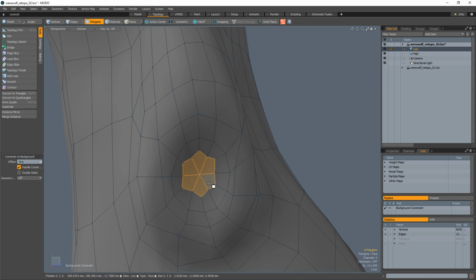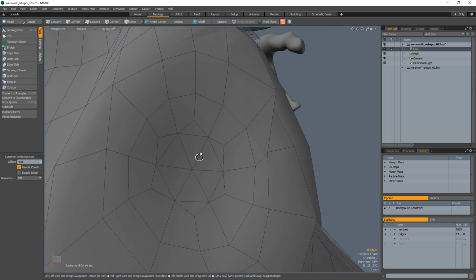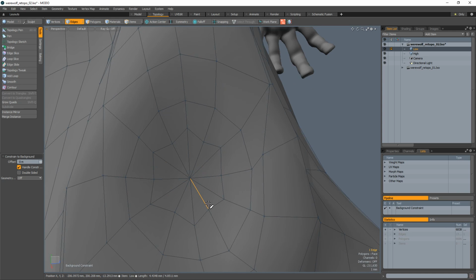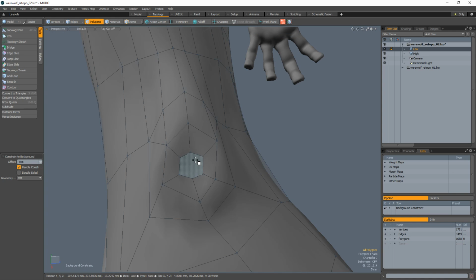So if you just select this and triangulate it, you might end up with a shape like this, or you might end up with all of these facing the other way. It's difficult to predict how it's going to triangulate, especially if it's auto-triangulating once it's imported into an engine. Things like Unity, Unreal 4 and CryEngine will have different methods for triangulating those types of shapes.